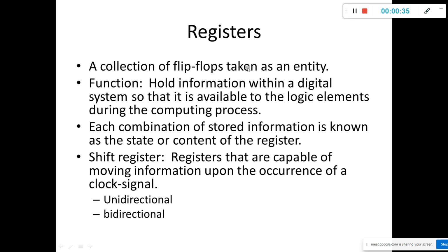A register contains a finite, countable number of flip-flops, okay? And each flip-flop is capable of storing a 0 or a 1 symbol. There are only a finite number of 0-1 combinations that can be stored in a register. Each combination of the stored information is known as the state or content of the register.